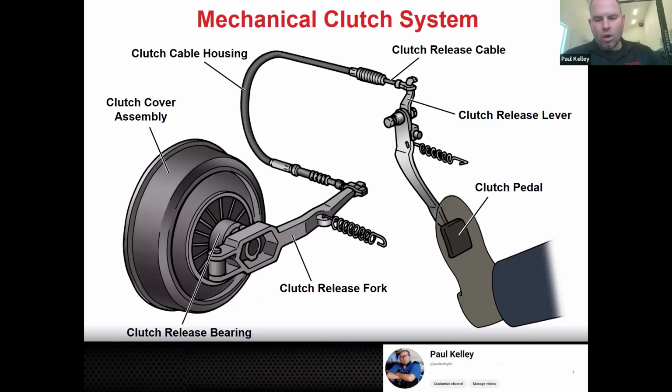Sometimes it slips. He had a whole list of clutch concerns and he came up with, it needs a clutch, obviously needs to pull the transmission. Well, I went down there and checked the cable and I said, hey, Jose, this is just a clutch cable. I can't tell you for sure the condition of the actual clutch, but while this clutch cable is binding, we can't even really test the clutch. So let's get a clutch cable. It was like $20. Put the clutch cable in, did the adjustment, because the adjustment's fairly simple. It's really just pedal free play. Make sure the pedal has 10 millimeters or 5 millimeters of free play, maybe a quarter inch. Set it, and then I said, it feels good to me, but have your son drive it.